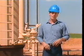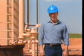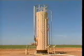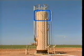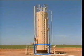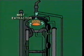Now that we've identified the major external components, let's look at the internal sections. As we look at the treater from top to bottom, the locations of the internal sections are the gas separation section, the settling section, the heating section, and the free water knockout section. Emulsion enters into the top section of the vertical heater treater. The initial separation of gas and liquids begins here. The mist extractor removes any tiny particles entrained in the gas stream before leaving the vessel.